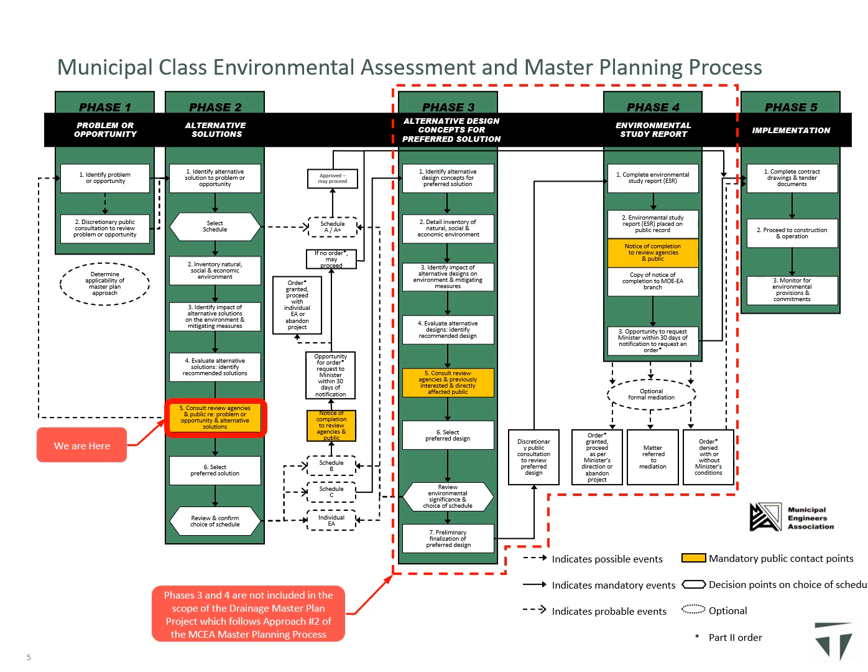The Municipal Class EA document classifies projects undertaken by municipalities into schedules based on potential environmental impacts. Schedule A and A+ projects are pre-approved projects that generally involve normal or emergency operational and maintenance activities that usually have minimal environmental impacts. Schedule B projects generally include improvements or expansions of existing infrastructure having minor potential adverse environmental impacts that must fulfill Phases 1 and 2 of the Municipal Class EA process before proceeding to implementation.